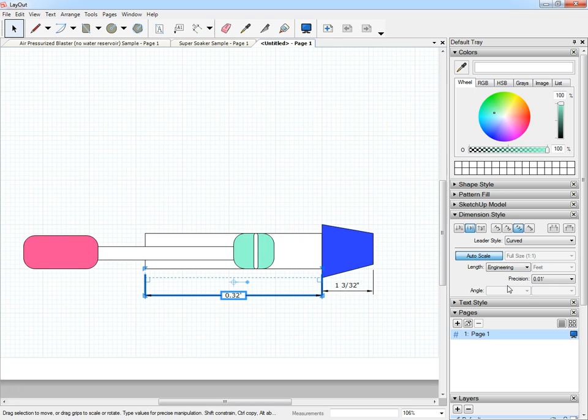You can change it to engineering. Engineering is going to be fine as well, but you need to make sure that you go down to the nearest. Well, that's in feet. So on the engineering scale, that's not going to work since the precision only goes down to, well, we can go from a foot down to each of these as well. But that's still not going to give us what I want. So let's go back into architectural, or fractional in this case. Alright, and then go to the half inch. Same thing with this one. Change this one to half inch, fractional. Okay, so 1 inch cap, 4 inch section, and so on and so forth. Now, if you go to the Grainger website, you're going to be able to get the exact sizes of all the fittings. Remember that this is just rough estimates at this point.